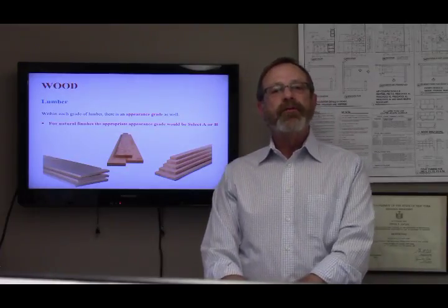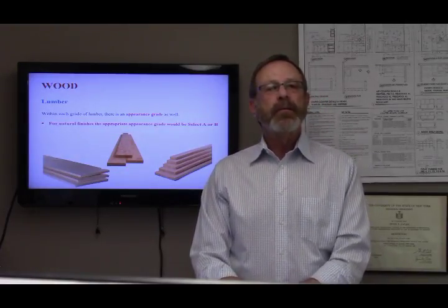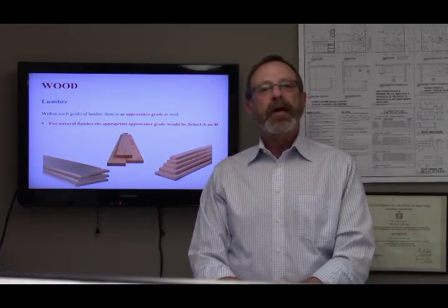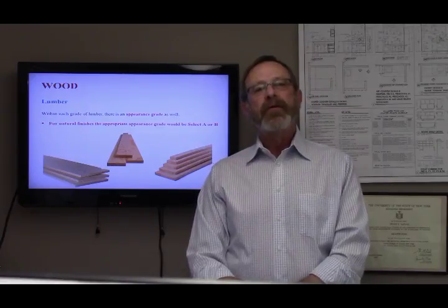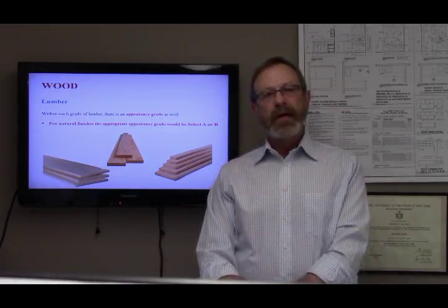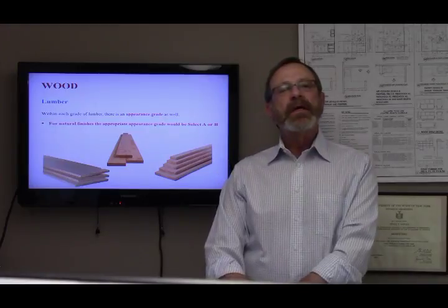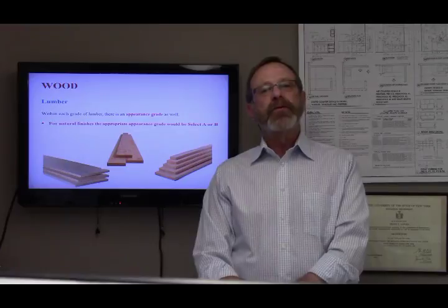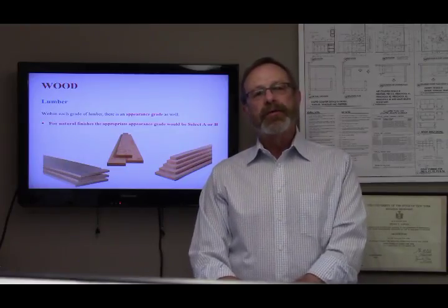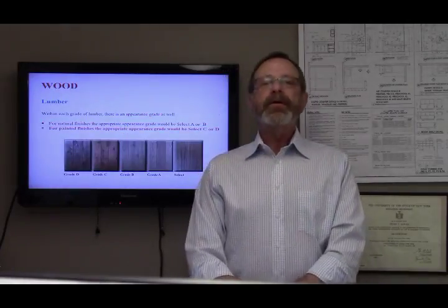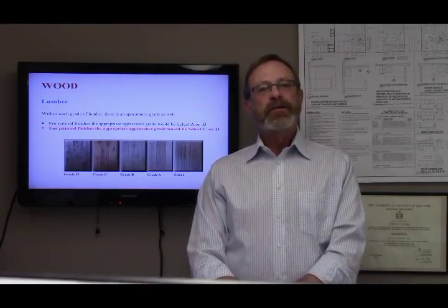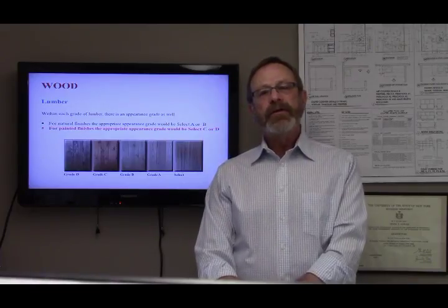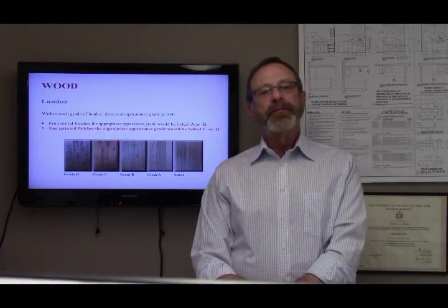Hardwood lumber is usually graded on the basis of the size and number of cuttings, pieces, that can be obtained from a board when it is cut up and used in the manufacture of a hardwood product. The upper grades provide the user with long, clear pieces, while the common grades are designed to be resawn into shorter, clear pieces. Material we call select is almost completely clear of defects, widely used for interior trim and cabinets.